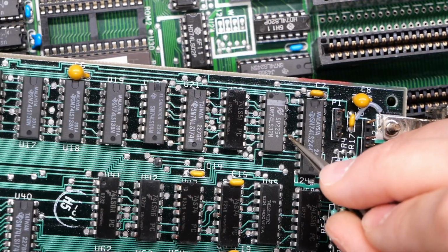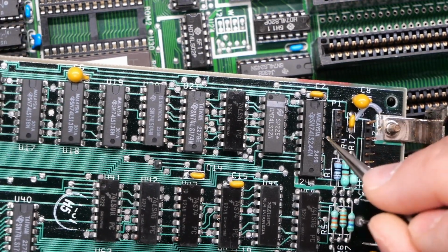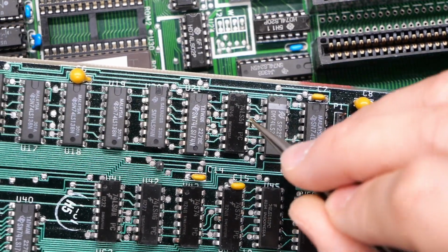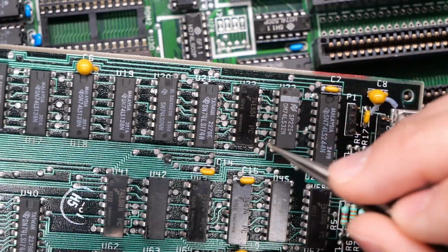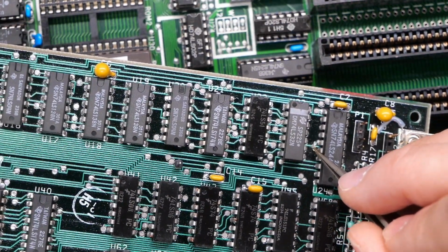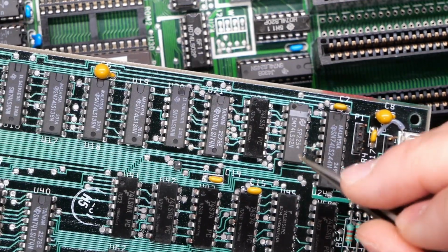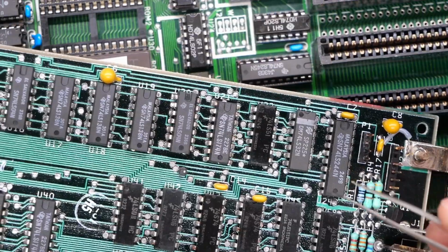To reconnect this, all you have to do is either put a little blob of solder on there, and if you can't do that, then you need to put a wire from pin 17 on this chip. And I think that was something over here on like this chip or this chip. I can't remember exactly which one it is, but you just have to tone it out from the left side of this little hole I made here over to the appropriate pin there. A bodge wire will just restore the original functionality.